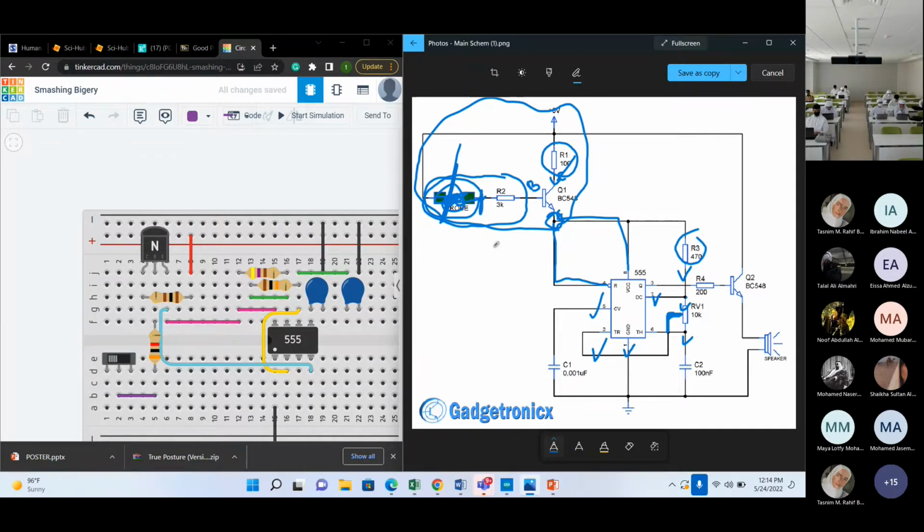Of course, as you guys learned before in tutorial 1, the common terminal is where your circuit needs to be connected. Okay, my circuit is connected. So where is my circuit? This whole thing is my circuit, right? So this point here needs to be connected to the common terminal of the switch, correct? This point over here. So this point is basically the resistor R2 connected from one side to the base of the transistor, as you can see here, and from the other side, it's connected using this wire to the common terminal of the switch. Are we clear?